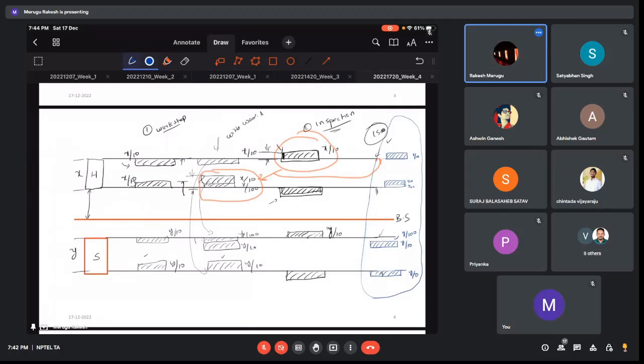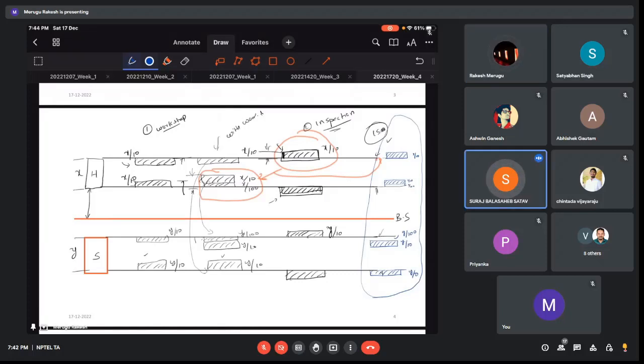In the upper line for shaft tolerance, that is related to the go gauge, right? Yes, correct. Maximum material limit, you see the maximum material limit every time for the go gauge. So you can remember it like go max, no go mini, just to remember if you are confused. Go gauges will always be designed for maximum material limit, and no go is always designed for minimum material limit. You can just remember these two terms.